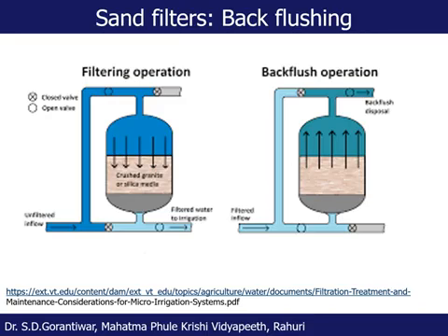If you consider this as the inlet at the top and the bottom as the outlet, then in the case of the filtering process, the first valve is closed here, so that water will go from this pipeline into the sand tank. This valve needs to be closed for this purpose, and then water will be filtered. This valve is open, so water will go into the outlet actually.